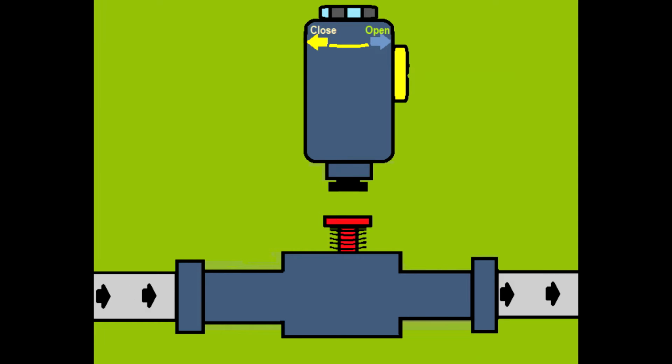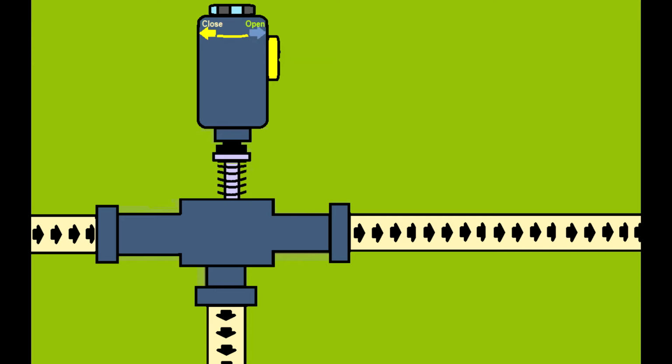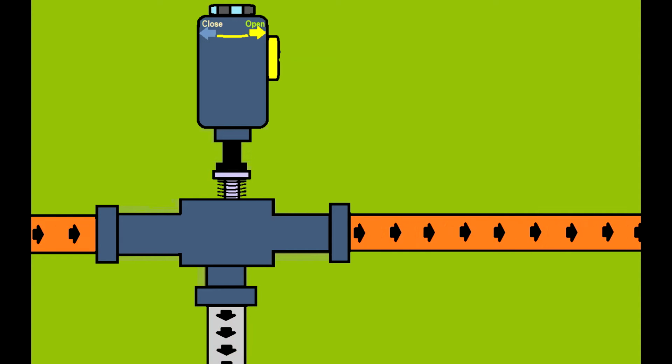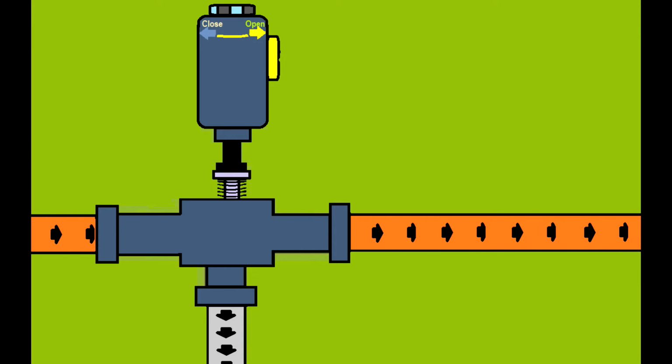Even if the actuator wants to close the valve, the shaft is seized because it's probably corroded, and you'll have a flow. Now, if the pump doesn't run in a system, we all know there won't be any cooling or heating agent flow to the system, and it would be a good idea for the PLC to run something like this to clean the shaft.